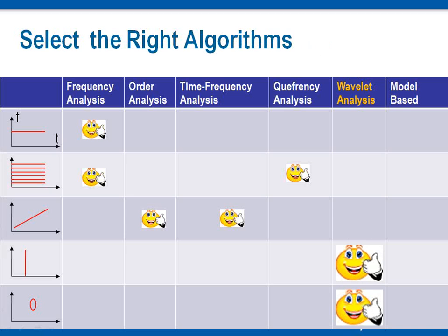Here are the highlights of wavelet analysis. Wavelet analysis is good for transient signal detection. Signals like spikes, edges, breakpoints, peaks or valleys can be detected using wavelet analysis. Multi-resolution analysis can also be done using wavelet analysis. It is easy to find signal events in different scales, for example both wide peaks and narrow peaks, using wavelet analysis.